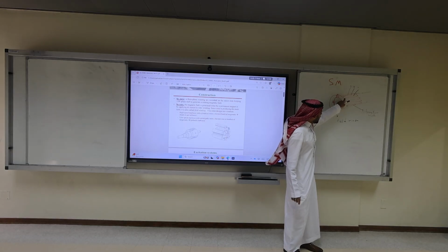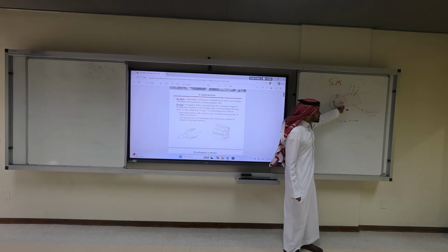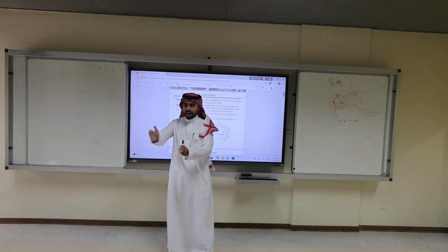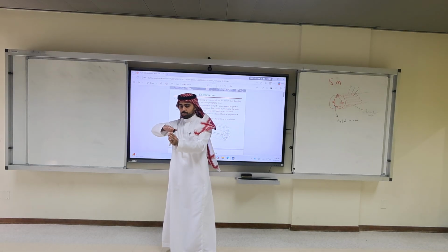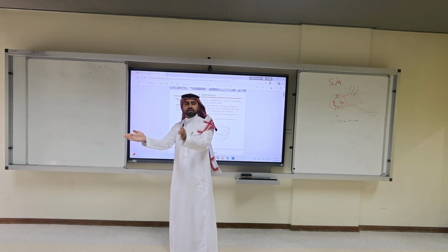The A winding is 120 electrical degrees away from the corresponding B. Sometimes you have A, B, C, A, B, C, A, B, C windings. But the matching A with the matching B have to be 120 degrees apart.